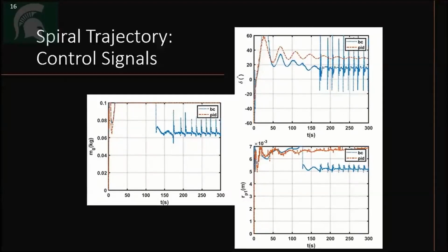The chattering is achievable but unwanted since energy use is associated with the derivative of the inputs. The PID controller doesn't see this chattering effect because in the simulation it never minimized the error to an area around 0, but from other simulations we can see that it also will experience this same chattering effect.